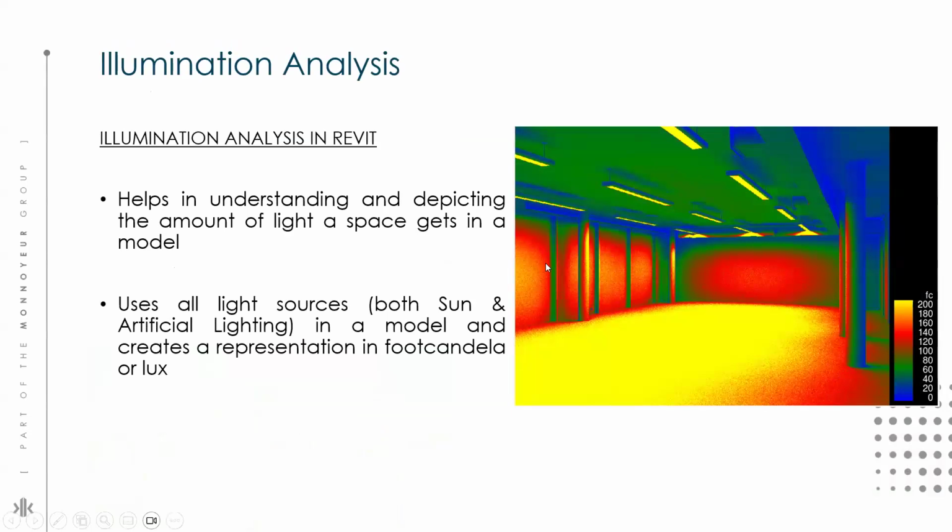If you need to develop certain interiors as well, where the light is reaching its maximum and where the lights are falling short, you can have those things within the interior portion as well. Similarly, you have to set a 3D view for the interior part by setting your cameras, and then again go to the cloud rendering option for utilizing those things according to your own locations. That can be done in two aspects. If you need the things in lux, that will give you an illumination on the basis of lux or foot candela. There are two predefined options that are applicable with Revit.